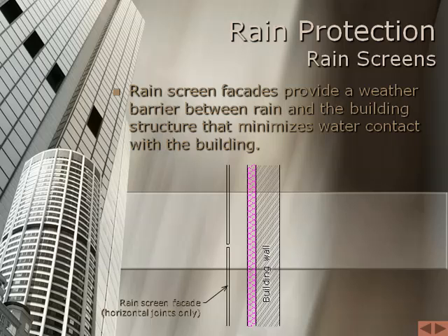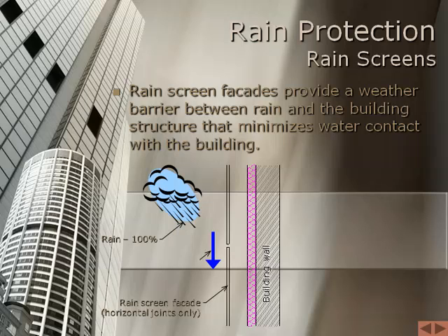For this particular rain screen system, the joints are also the openings providing air pressure equalization in the air barrier. With this rain screen system, the majority of the water comes into contact with the facade and gravity flows along its exterior face, nearly 95% of the water. Over 5% of water penetrates the joints in the rain screen but will gravity flow along its interior face.